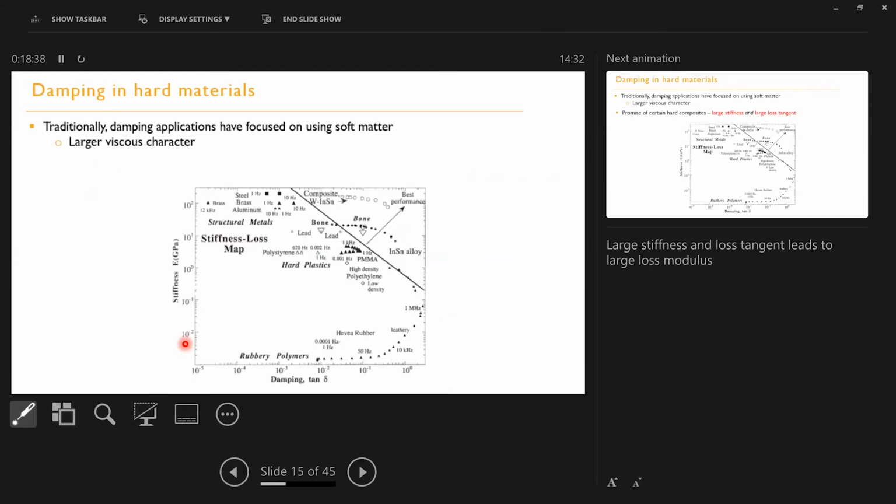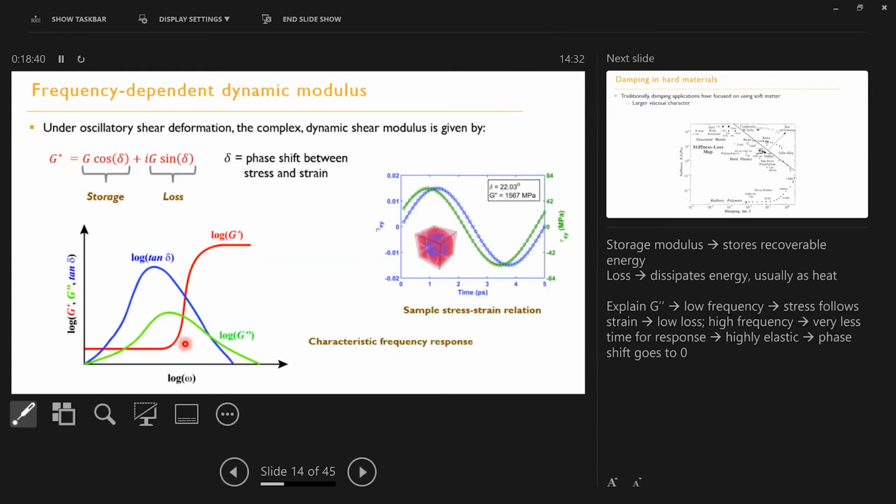And one more motivation: amplitude is again very important. There are two regions in viscoelasticity called linear viscoelasticity and non-linear viscoelasticity. When you have small amplitudes, we are in the linear viscoelasticity region, which basically means that the strain amplitude is not important. But when you go to very high strain amplitudes, it will depend on the amplitude also. That we also study later on.